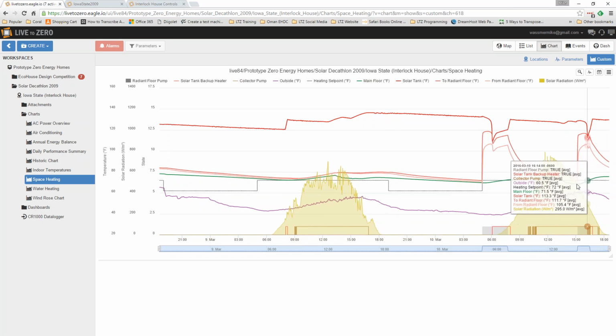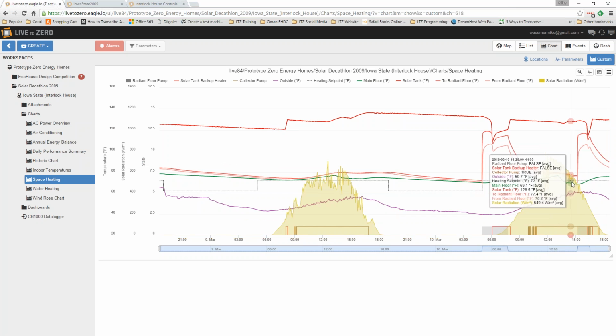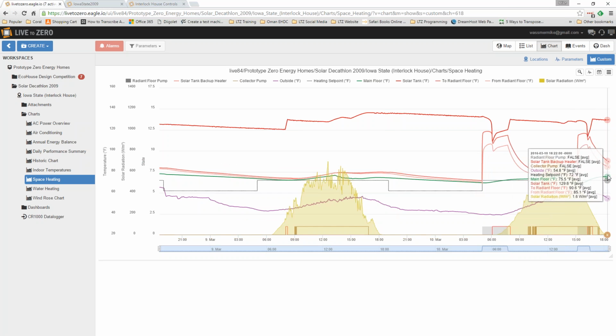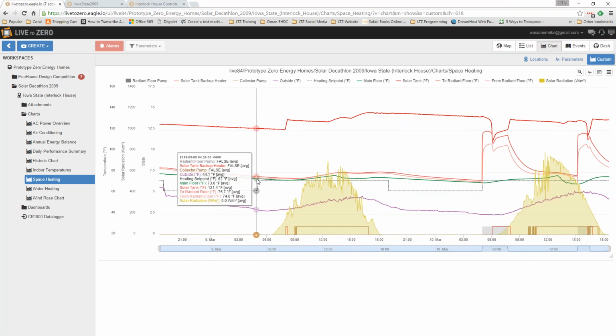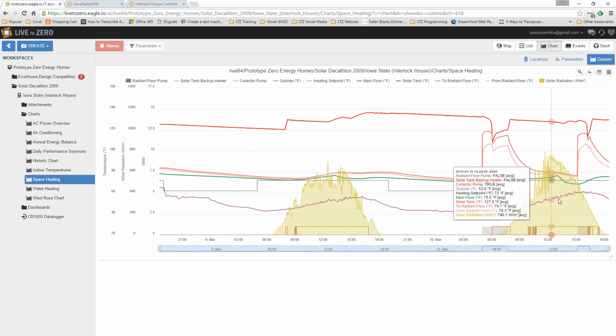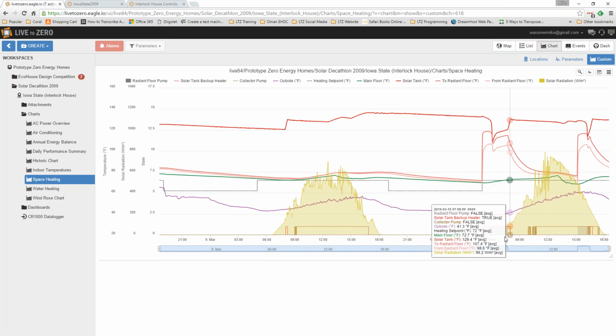But now, because the building has lost all that heat, which is fine, to stay comfortable you have to do that, it's only gotten back up to 75.5, and it's probably going to drop below the heating set point. So unless we disable the heat, it's going to turn back on in the morning again. And the question is, is that necessary? It all depends. Go ahead, Marika.